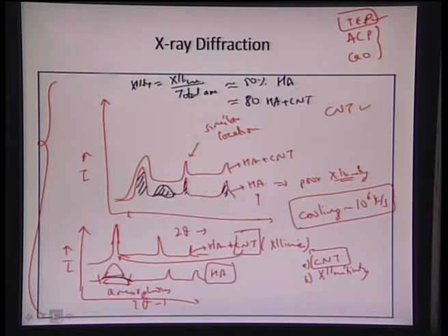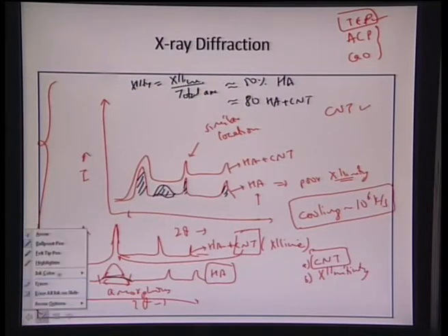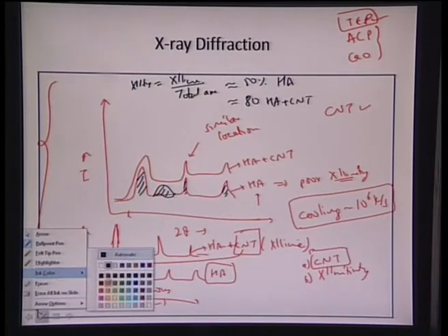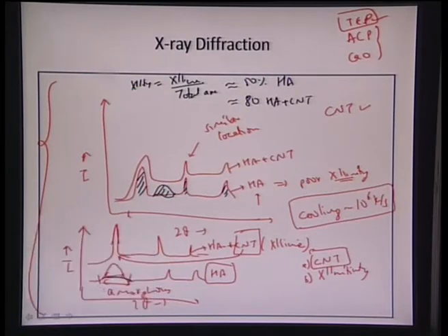for hydroxyapatite plus CNT. So that clearly tells that CNT is playing a part in increasing the crystallinity of this particular structure. That is what is so critical about this part: CNT serve as sites for supplying some additional heat to the hydroxyapatite and making it much more crystalline, letting it crystallize for a longer duration of time. Once the plasma spraying is done, the whole powder stays in the plasma plume for a couple of microseconds, and that time is not sufficient for the hydroxyapatite, and again it undergoes very rapid cooling, of the order of 10 to the 6 kelvins per second.